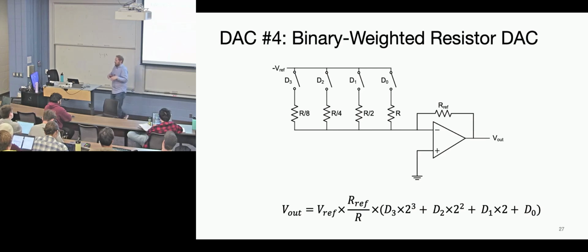So in silicon, you basically lay out a resistor as a functional block, usually poly or a serpentine metal structure, and then you can make clones of that, and it's easy to make sure they're all the same size. You lay them out to be the same size, and you have some that are double, where you just wrap them around. In silicon, you're trying to make the resistors all the same size or multiples, so that when you go through process manufacturing, they all change similarly. So if they're all a little bit smaller in resistance, you want them all to be even.